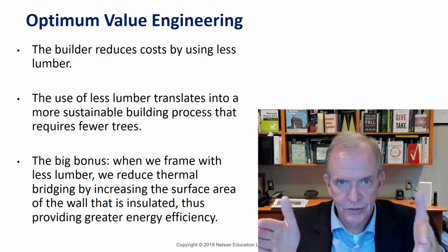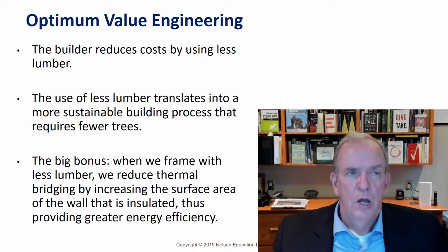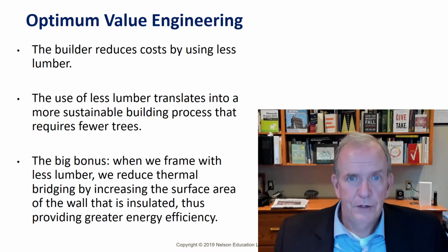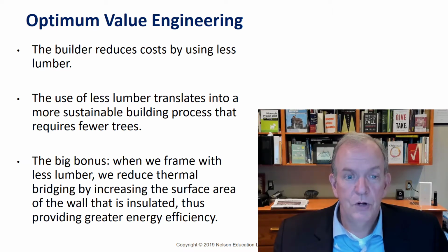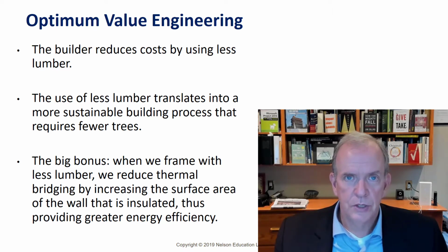So now you have this concern of lining up the trusses exactly with the studs, which can often be difficult. What if your studs are at 19.2 and your roof trusses are at 24 inches? They're not going to line up, so you'd have to put your roof trusses at 19.2 inches.